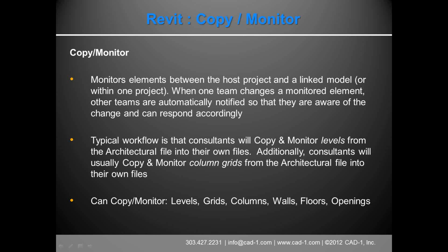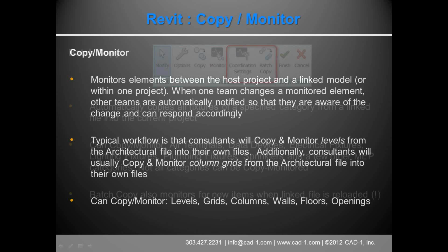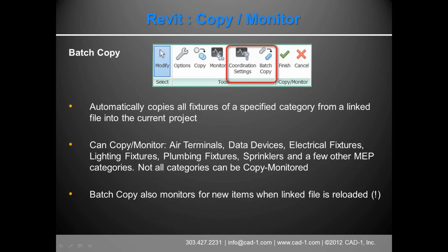Typical workflow is that consultants will copy and monitor levels. Almost everybody does levels from the architecture file or from structure, whoever is controlling the level of the building. They copy monitor that into their own files. And usually, the consultants will copy and monitor the column grids, the grid lines from the architects, or if structural is managing that, from another file into theirs. You can also copy monitor columns or walls, if those are important, or floors, as well as openings. That's the standard copy monitor tool.